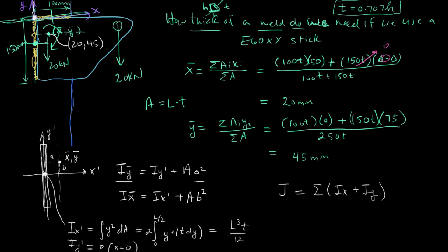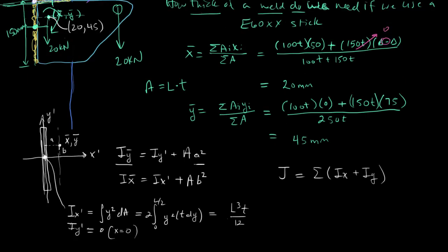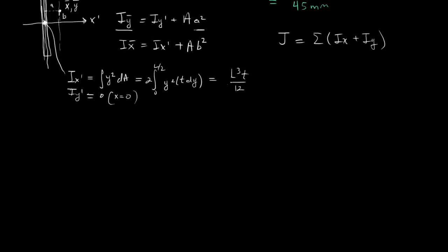In this case, we have in-plane stress, so it's just replaced by an in-plane downward force, which will cause a shear, and then a torsional torque, or a torque that causes shear stress. Okay, so then with that review in mind, we can take a look at the top weld.